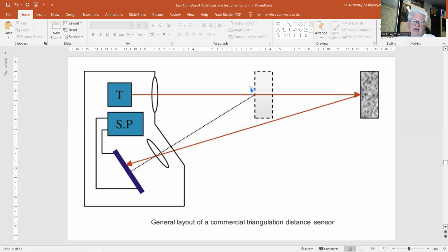The instrument either contains a display or provides an electrical output. Measurement ranges run from a few millimeters up to several meters. Reproducibility is in the range from ±1 to ±10 micrometers. Size reduction of the optical system is another issue to increase the versatility of distance measurement